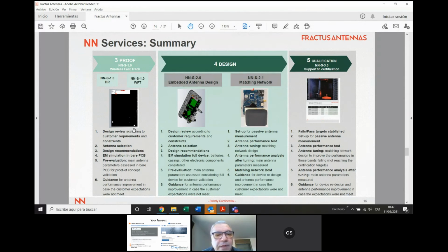So you cannot place the antenna on the metal. And we have some customers, some applications, where we have found a solution. Always, if you put the metal a minimum of 5 millimeters away from the antenna, then you can work with it.